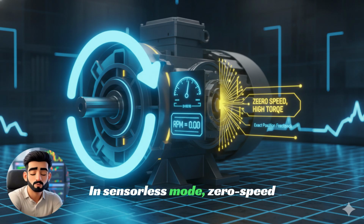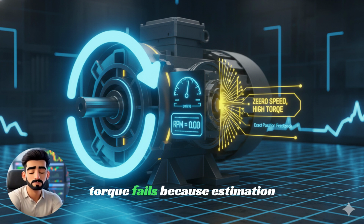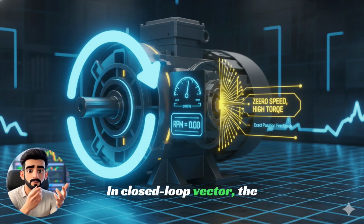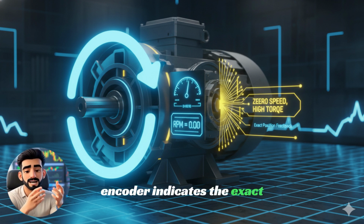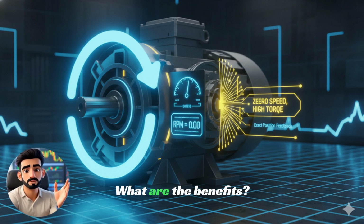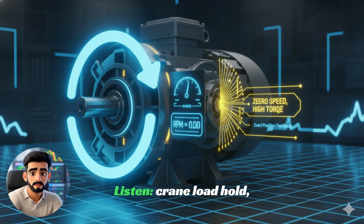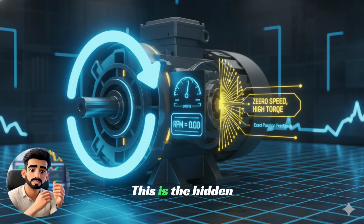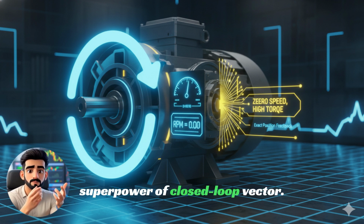In sensorless mode, zero speed torque fails because estimation does not work at zero speed. In closed loop vector, the encoder indicates the exact angle of the shaft. This allows the drive to hold torque even at zero speed. What are the benefits? Listen. Crane load hold, hoist safety, elevator hold, conveyor rollback prevention, extruder smooth startup. This is the hidden superpower of closed loop vector.